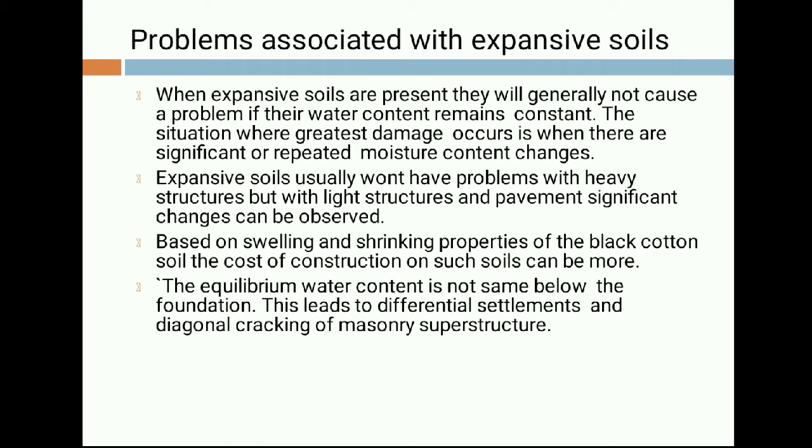In case of the same structure also, there can be moisture variation at different points, and based on that moisture variation, the foundation may experience different settlement, which leads to differential settlement of the superstructure.